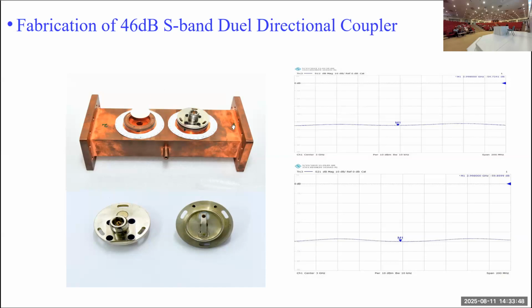But when RF is passing through this waveguide in this direction, and if these two slots are spaced at lambda g by 2 or their integer multiple, then their antennas are almost identical in position, and their coupling will be 2 to 3 orders different.